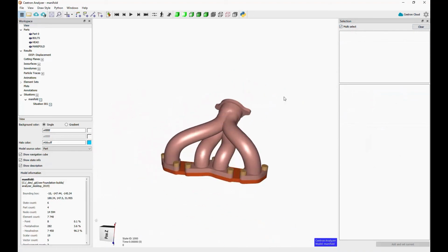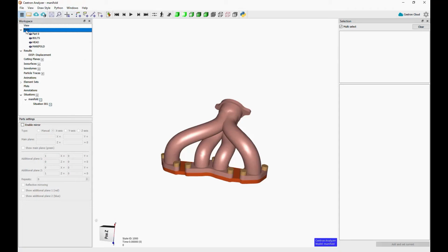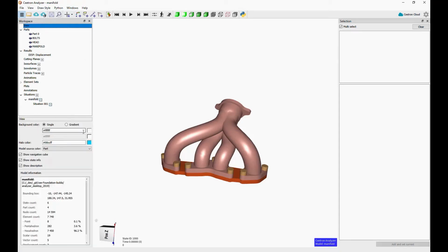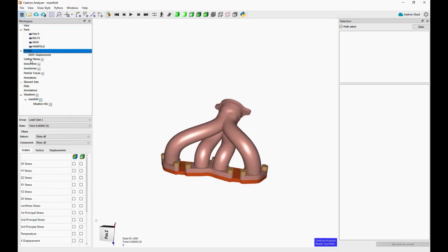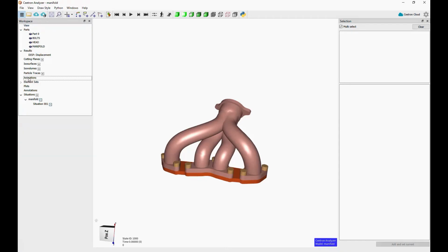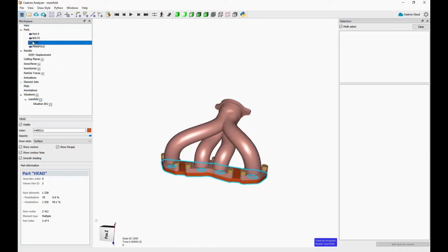The next docking window is the workspace. The top pane contains the model's feature tree. This is where all of the model and view data is exposed, and where you will be able to configure the display by selecting results, adding cut planes, setting up animations, etc. The bottom pane will show the properties of the currently selected item in the feature tree, allowing you to specify this item according to your needs.